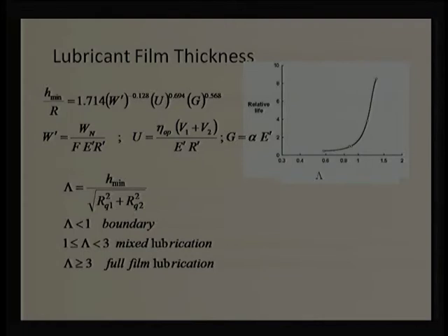Whichever oil you choose, we need EP additives and anti-wear additives in those gears. If you are not able to use those additives, performance will naturally be worse, towards boundary lubrication, and relative gear life will be much lesser. But from 1 to 1.5 there is a substantial, significant jump in relative life.